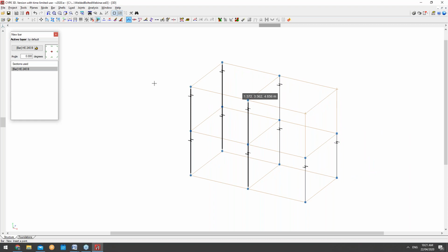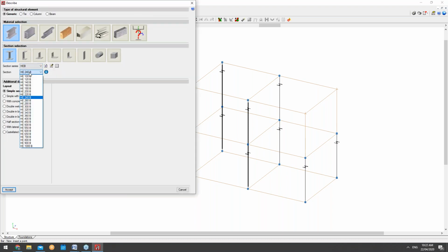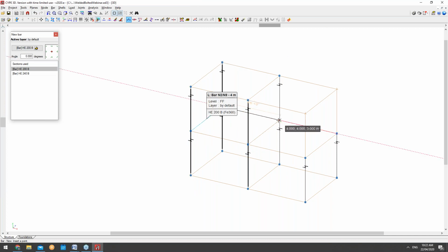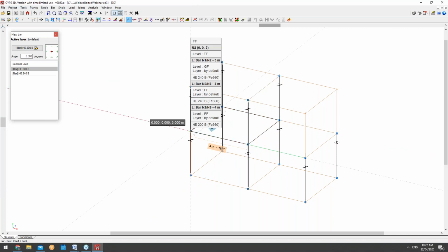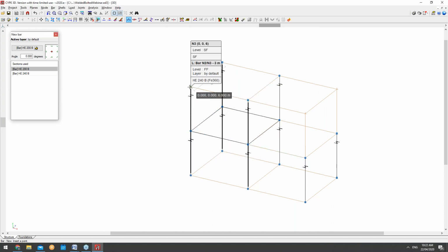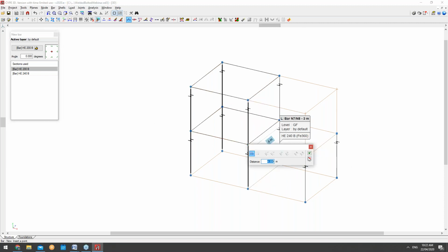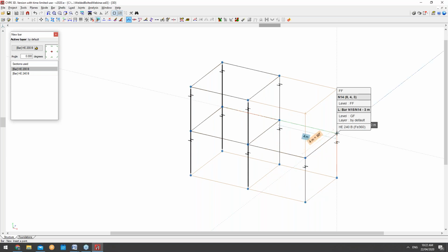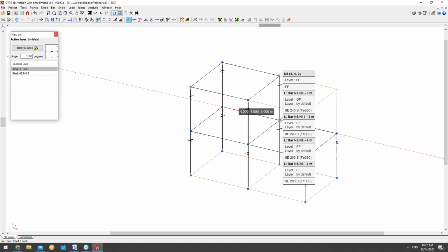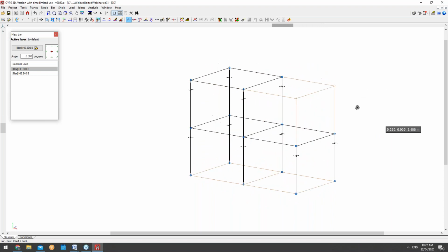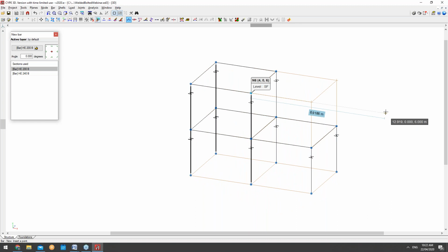Now, upon completing that, we can have a look at creating another one. Now, instead of HEB 240, let's go for 200 with no fire resistance. This should be fine. So I'm basically just connecting my nodes here. Now, this has to be done before introducing our connections. Now let's have a look, holding shift and moving around. You can see that I've connected them as well.